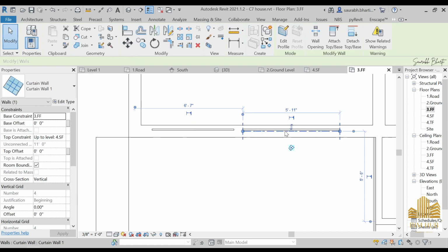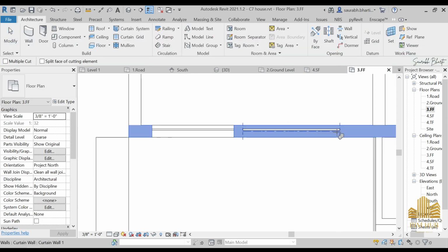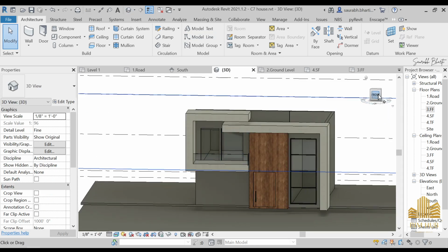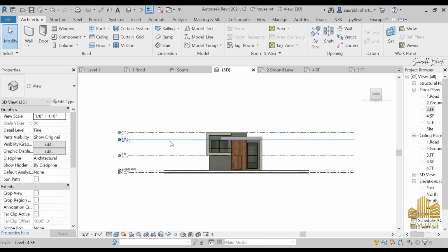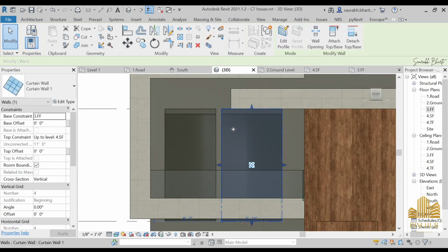Now we have to cut this geometry, so select this one, cut, select your wall, then this one, again select your wall, select this one, go to cut, select your wall, then you will find, actually you can see that there's a line coming over here, so we have to select this line, and now we have made the cut. And now that we have made the cut, again go to the front view, and you can either increase or decrease the size of it.